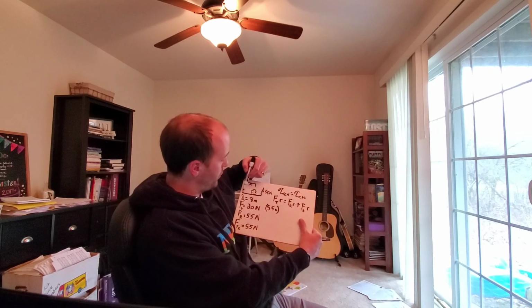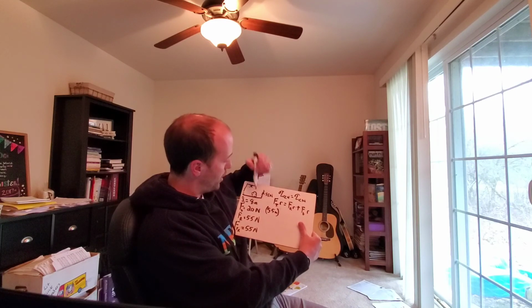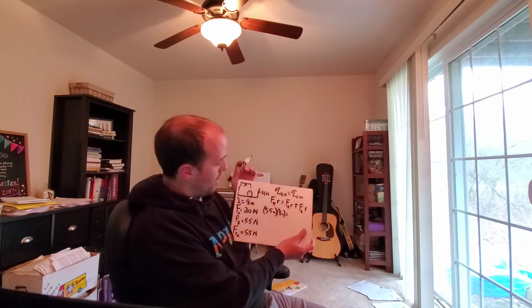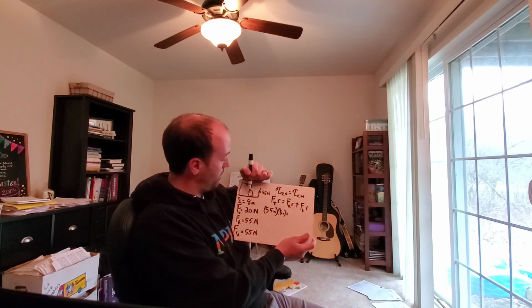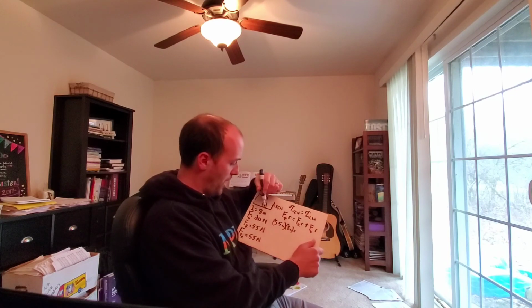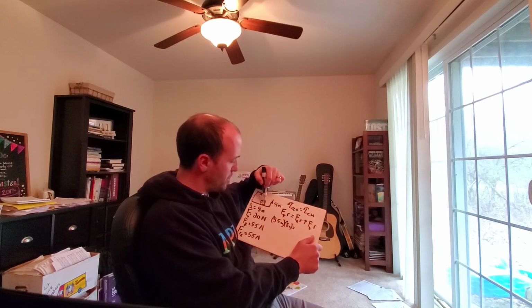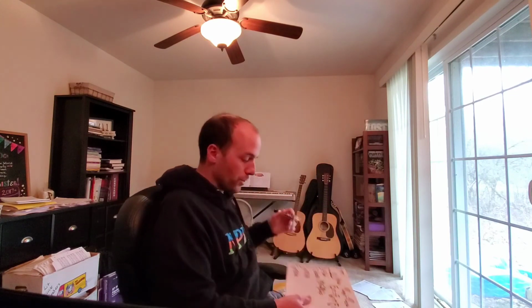So let's plug some values in. We know that force of tension is 55 newtons. And the moment arm for this force of tension over here is the full length of the beam, 8 meters. Force of the rock: we know the weight of the rock, 55 newtons, but we don't know the moment arm for the rock.